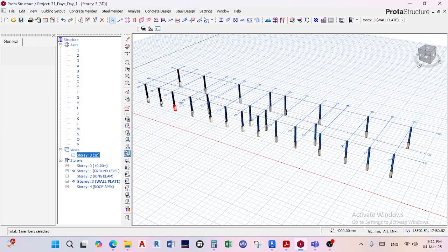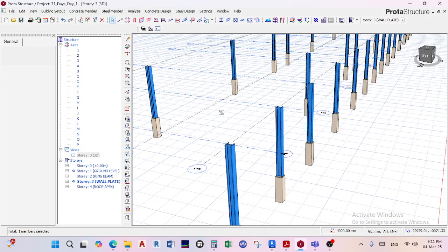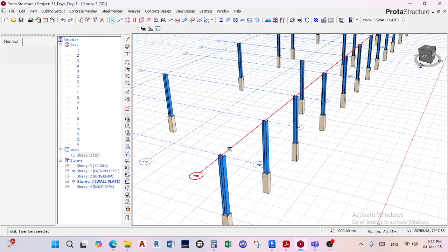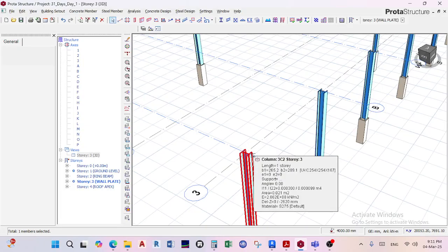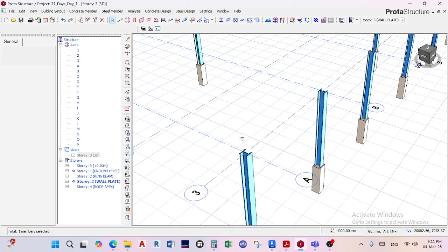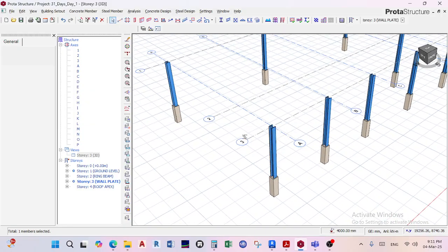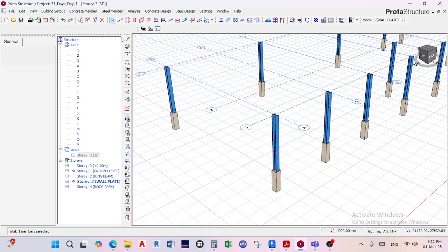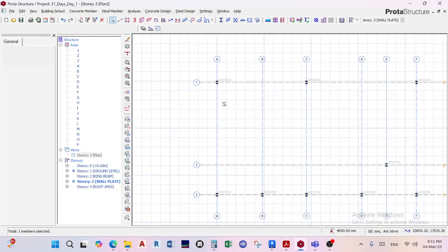You would place maybe a timber truss, but then you would have to think of your connection. How does the timber connect to the steel? Of course, maybe you'd have to use a weld where you thread into the wood and then you create a base plate, and now that base plate will be welded here. But yeah, it's possible, but not the best. Go back to plan. So we're using a steel truss because I can weld steel and steel. I cannot weld steel and steel by the wood.